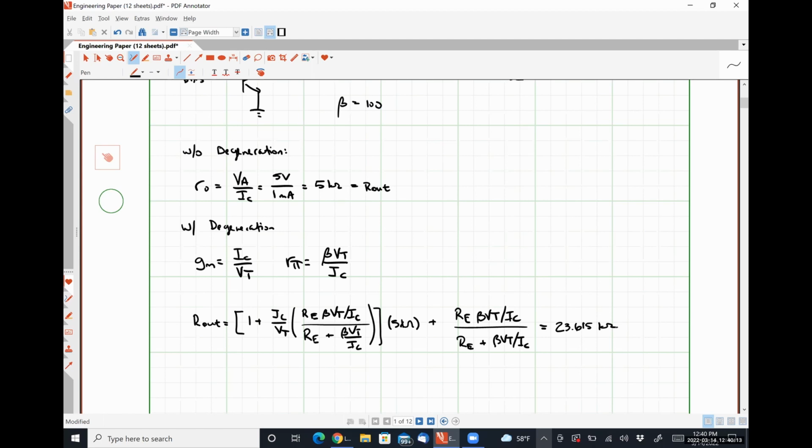And so what that means is that this resistor RE will have an associated voltage drop over it, which depends on the collector current, IC, right? Since we have to maintain a certain value of VCE in order to keep our device in saturation, this can be problematic.